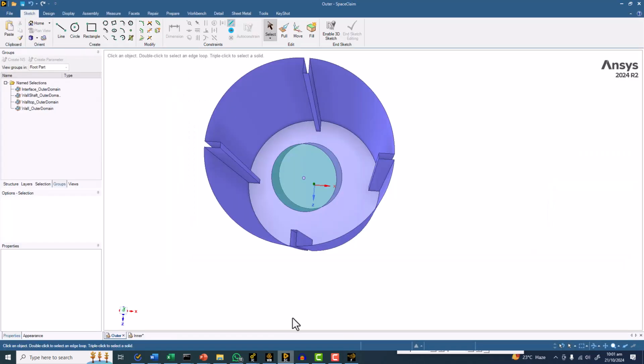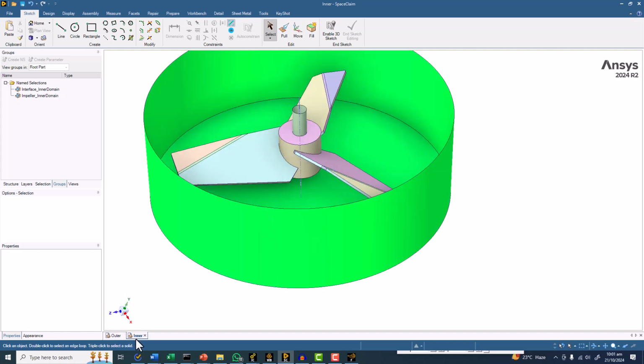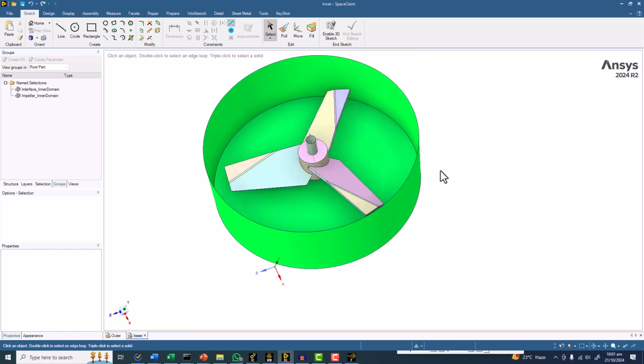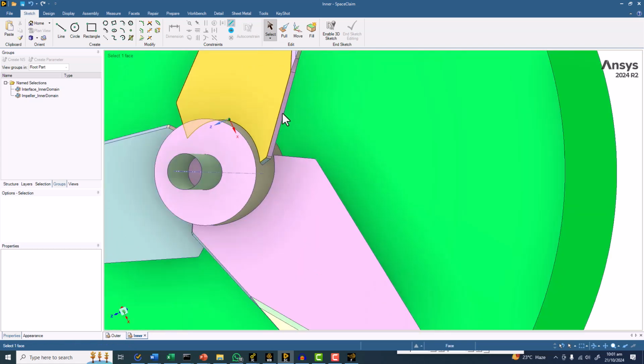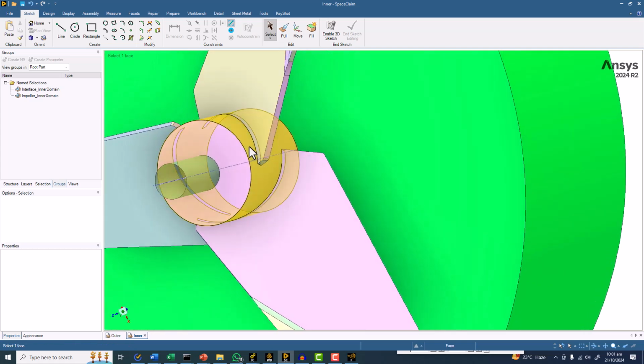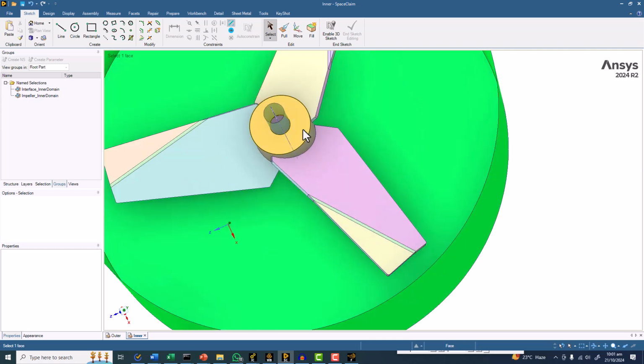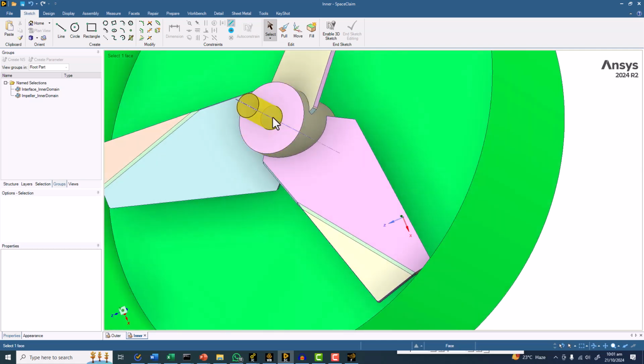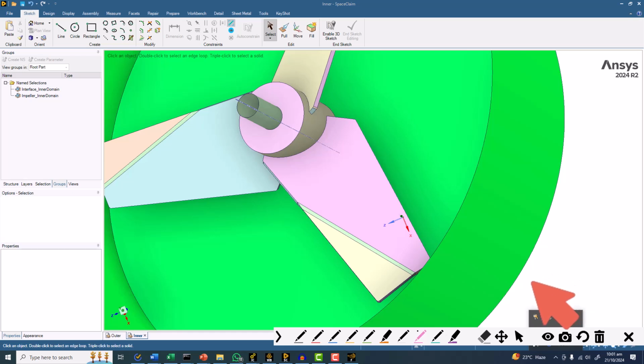The geometry that we are modeling is the impeller of the mixing tank that you can see here. It has some complicated geometry, and because of the requirements of the prism layers, and the number of layers being 10, it can create stair stepping. Stair stepping actually means something very simple. I'm giving you a very simple explanation here. At some locations, for example, this is our geometry, the wall, and here we have the prism layers.